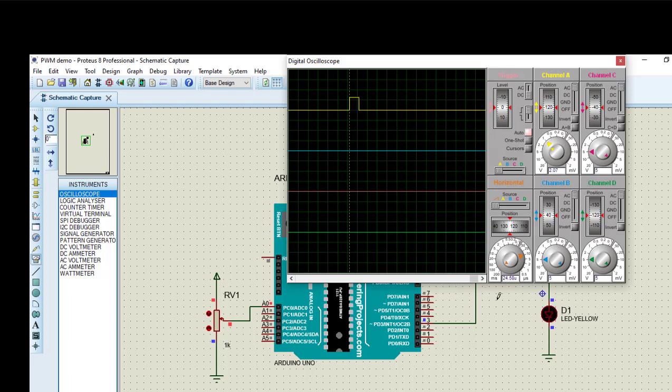But now here in Arduino, you just use the analogWrite command, which is used to do pulse width modulation, and it takes the pin plus the duty cycle, and that's it. You're able to toggle the pin at the different duty cycles that you're looking for.